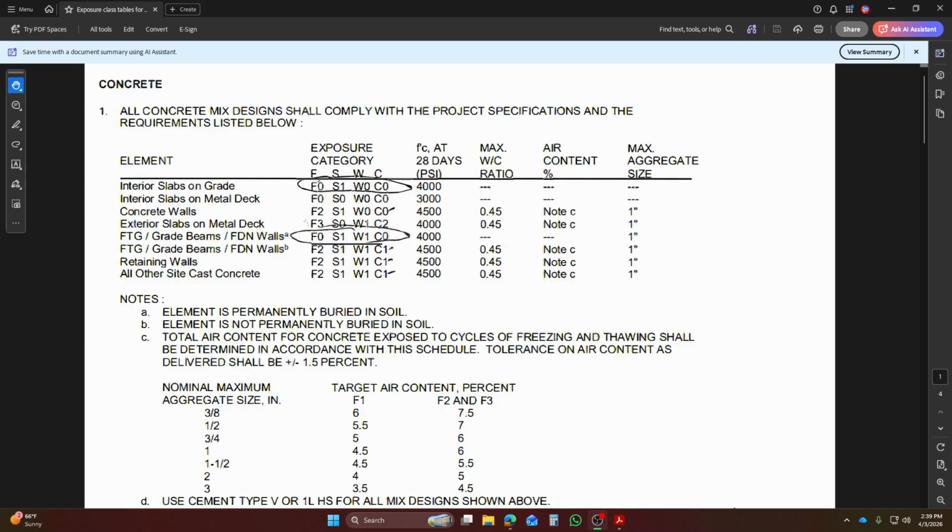So you'll have the same PSI, same exposure requirements, things like that. So multiple 4,500 mixes could very well be used for different things in here because it meets the same specs here. But the project spec itself varies from project to project, not necessarily what the mix design that Suncor has, because each job has its own set of requirements.